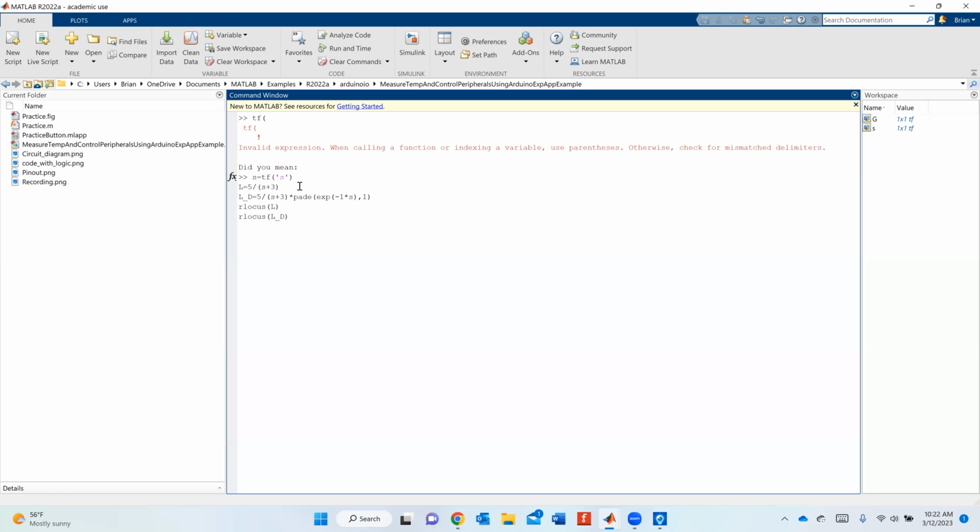And what we need to look at is what it's going to be like. So we're going to compare the two specifically and see what the actual response will be for a root locus plot. And we're going to see about our gain margin. So I also want to see the margin of L. So we notice, hey, did the gain margin decrease or increase when we added a delay? And so let's just plot all this.